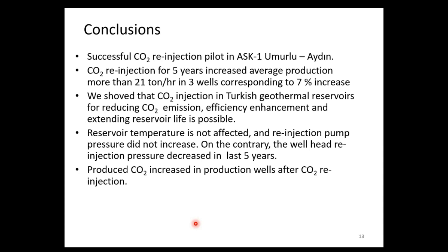Today, re-injection over 5 years increased average production by more than 21 tons per hour in the 3 production wells connected to this power plant. It was a 7% increase in the brine, which actually pays off the cost of NCG re-injection.